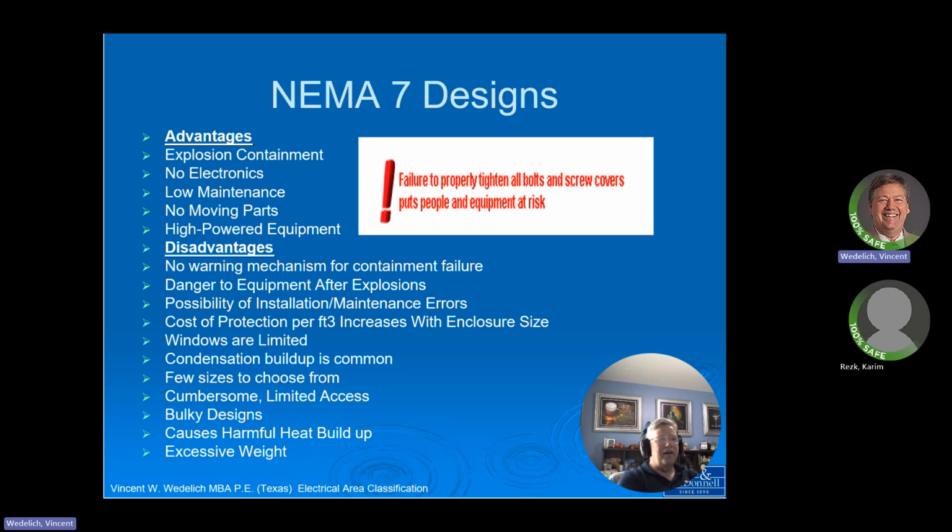I've designed offshore class one, div two rectifiers that were up to 800 amps using a box like that. The way I did it was I machined the outside and I machined the inside. I bolted the SCRs to the inside, and then on the outside, I put a water cooled heat sink that we made. It worked really well. If it's small enough, I can just put a heat sink that's air cooled, but rarely, that would be like 50 amps or less.